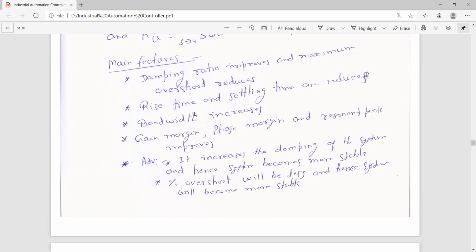Steady state error gives the idea about the accuracy, whereas rise time gives the idea about the transient response, and settling time about the steady state response. The larger the rise time, the more sluggish the system, so it is inversely related to speed. Similarly for the settling time. So for a faster system, rise time must be smaller and settling time must be smaller.